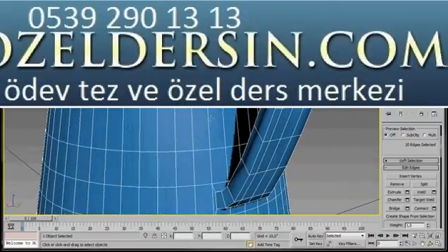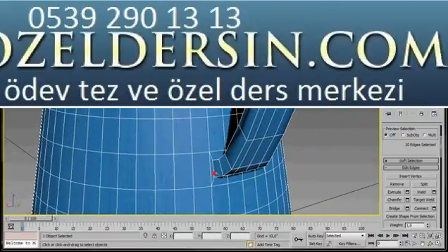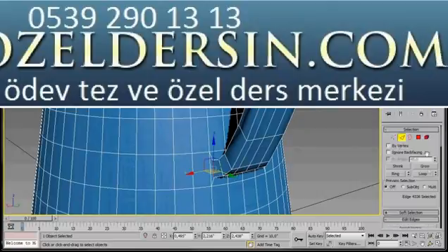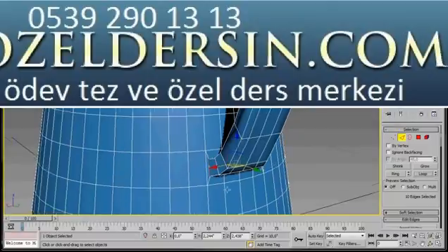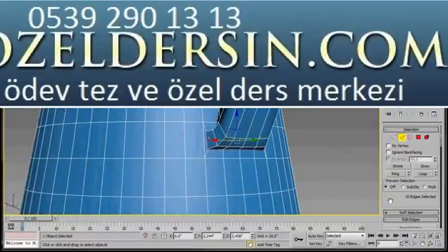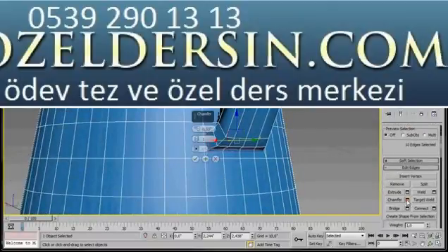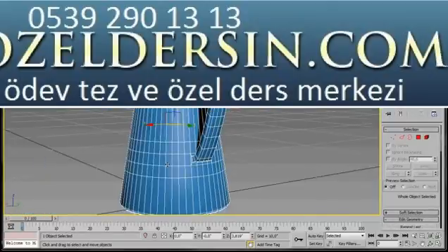We're going to do the same at the bottom end of our handle. Let's click on this edge, then we'll come over to the panel and click on Loop. Now we can scroll down and click on the small settings icon for Chamfer. Now here in the caddy, we'll just leave it at 0.03, then press OK.